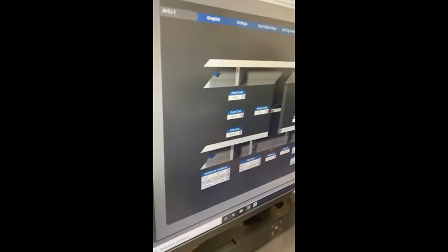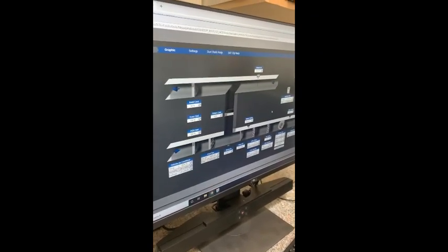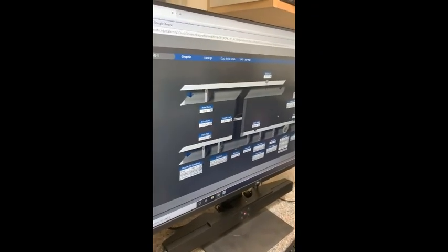Now I remember. Basically, the way the heating load works is one command will go from basically no demand. There's one thing trying to control the supply air temperature, and it will only use that hot water valve to bring the supply air temperature to that set point if it needs to. So say if the supply air set point is 50 or something, and it's like 30 degrees outside, then it tries to maintain that set point, 55 or whatever that set point is. Sorry, I misspoke.